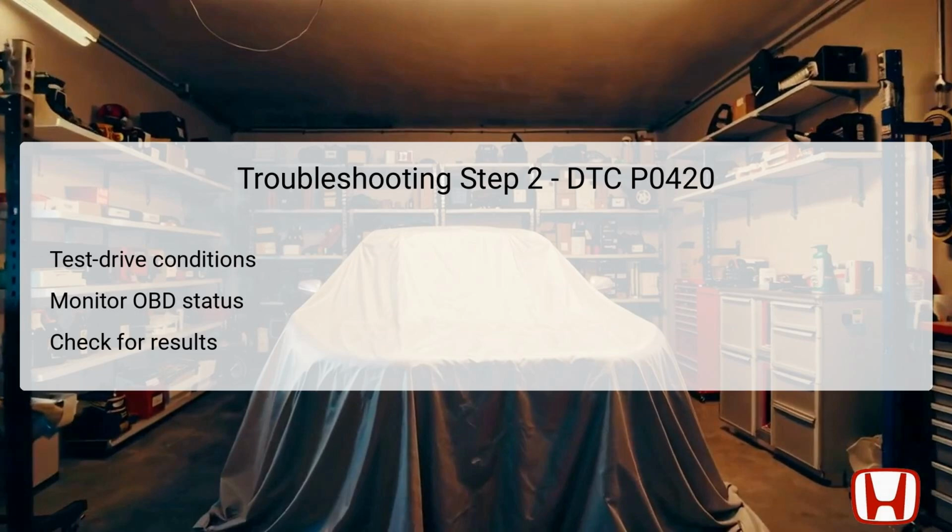minimum of 5 minutes. During the drive, the vehicle should also be allowed to accelerate to 55 to 75 miles per hour, 90 to 120 kilometers per hour, for 10 seconds, and then decelerate with the throttle fully closed. This sequence should be repeated 3 or more times to validate catalyst efficiency. After completing these driving conditions, the OBD status must be monitored to check if the DTC P0420 shows any change. Depending on the results noted by the HDS, further action may be needed based on the status indicated.